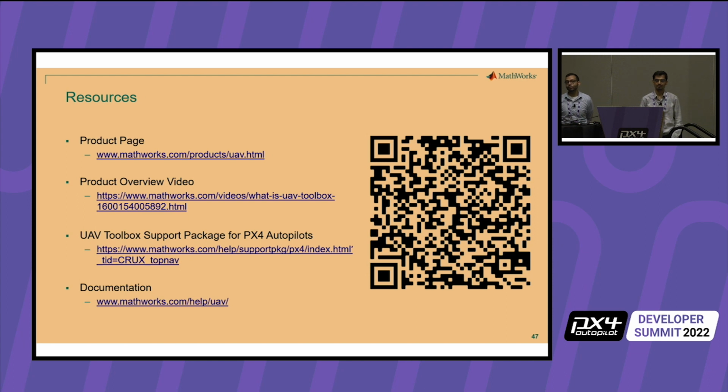So you can build it entirely yourself using Unreal Engine. You can customize both the environment and your drone model, the platform. You can bring in meshes in Unreal Editor, and for that you have to download Unreal Editor separately. Just for visualization, using the pre-built city scene block and the pre-built platforms, you don't need to do anything.